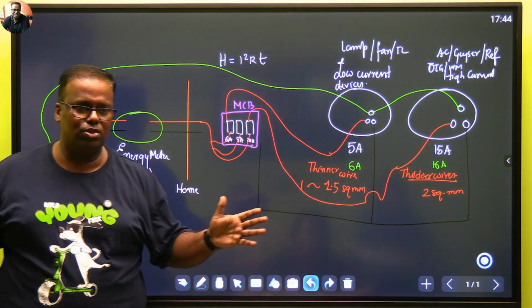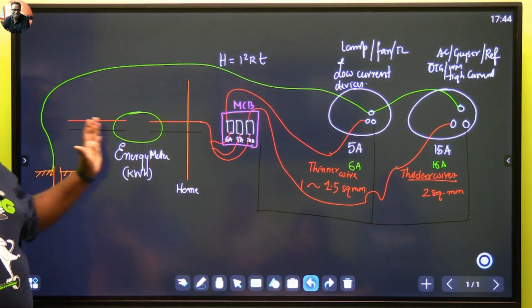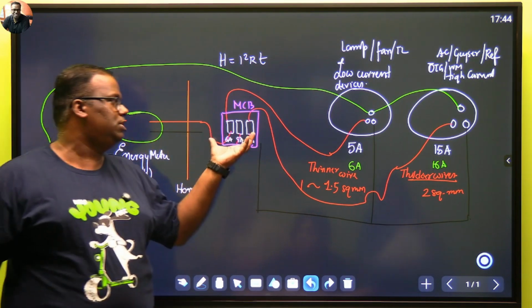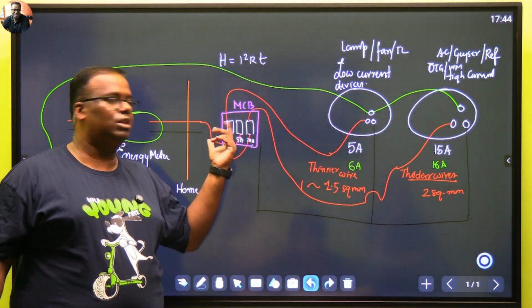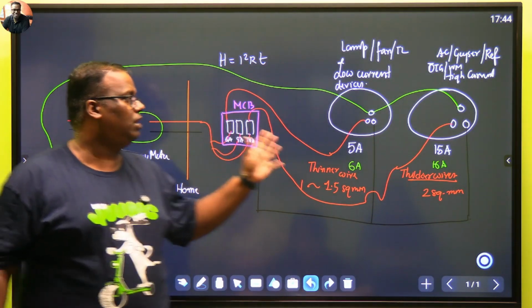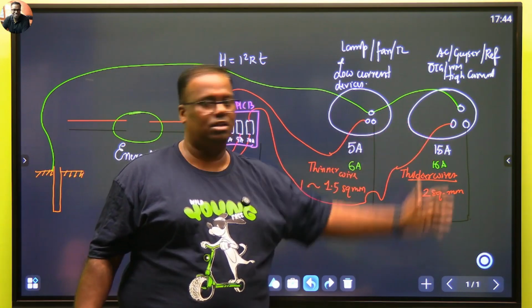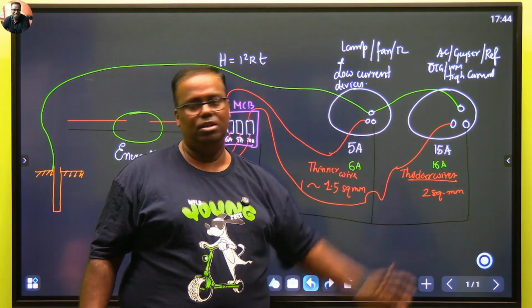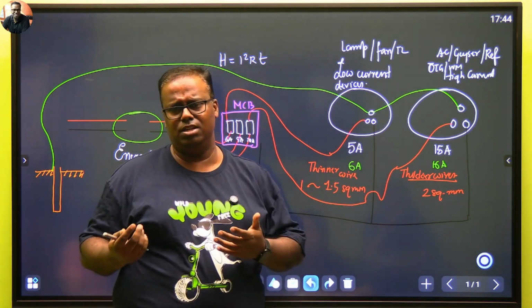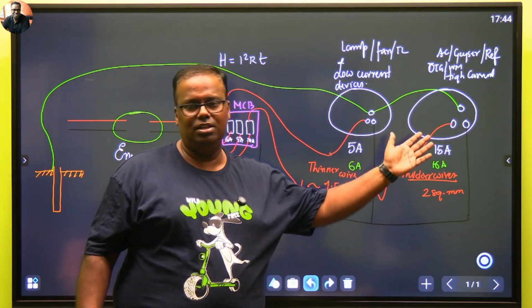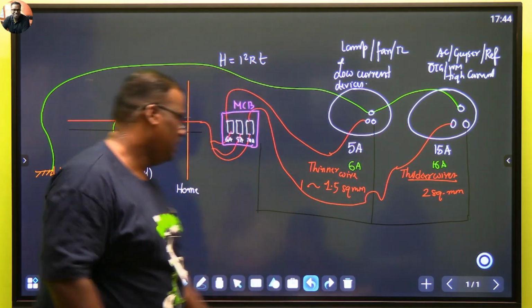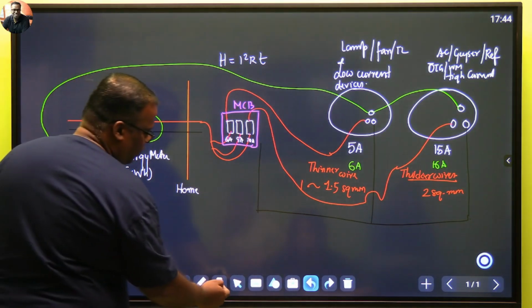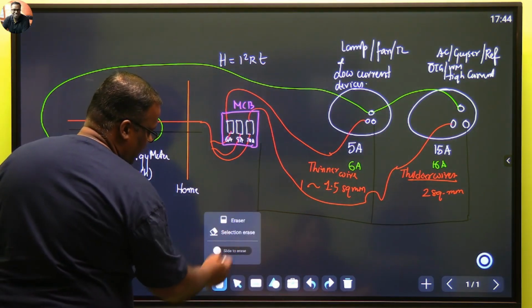This concludes actually your syllabus. Your supply comes through the meter box, comes through a division of miniature circuit breakers. All these, which in your normal language you call strips. These strips are then guided to, and the house is calibrated into two things called 16 ampere lines and 5 ampere lines. In your book it is 5 and 15. In reality it is 6 and 16 amperes. ठीक है, इतना ही. अब देखते हैं reality में how this thing happens.